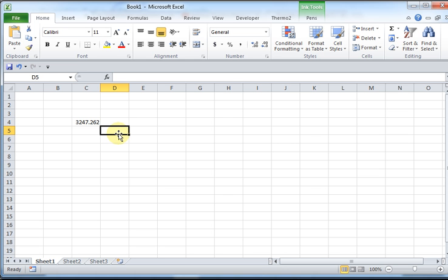All right, so what I would do is do something like this. I always build it like this. State, I make a little comment in that cell that's not evaluated. And then I say pressure in kilopascal, and then temperature in degrees C. This is my style. And then maybe enthalpy in kilojoules per kilogram. I like to put as a comment what is in that column plus the units for that. Entropy, kilojoules per kilogram Kelvin.